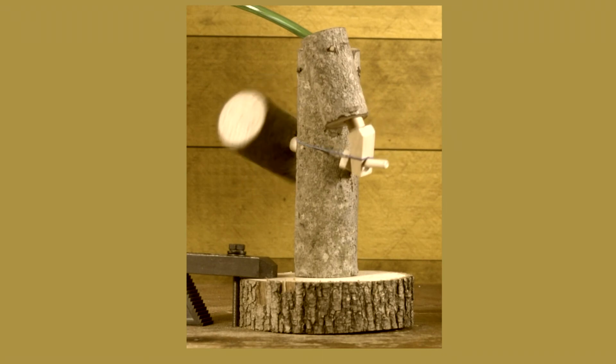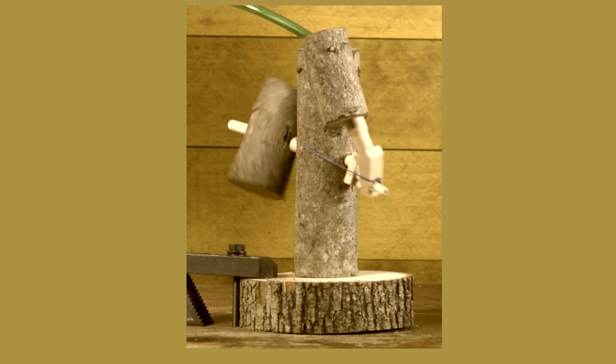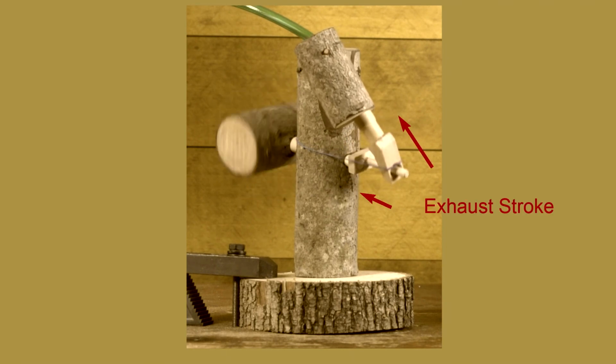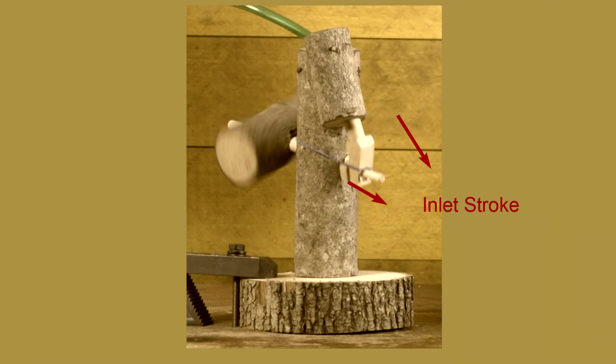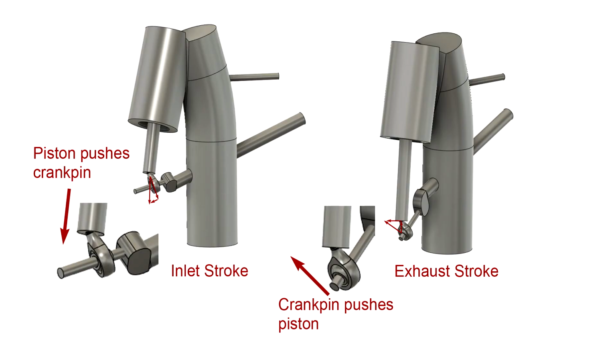The only thing that remains is to try to better understand the need for the rubber band. It's a little difficult to illustrate, but it seems that the net force along the crank pin — remember that the flywheel is driving the engine during the exhaust stroke when the rubber band is needed — is insufficient or even in the wrong direction to initiate rod end motion back toward the crank. Even if it were in the correct direction, it may be that the axial force component's angle to the crank pin is too large and there's an axial friction lockup condition.